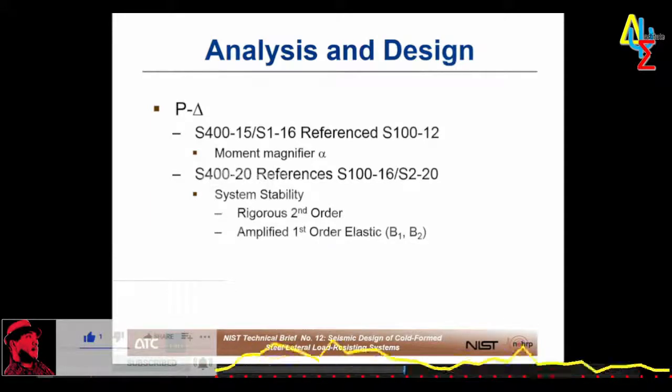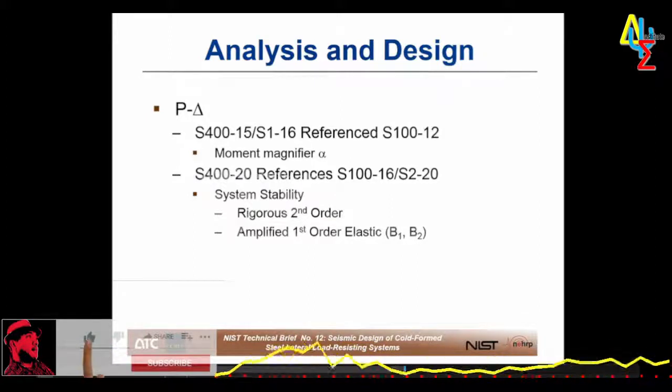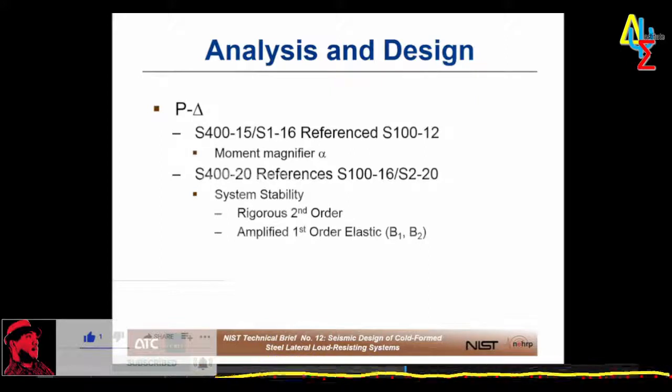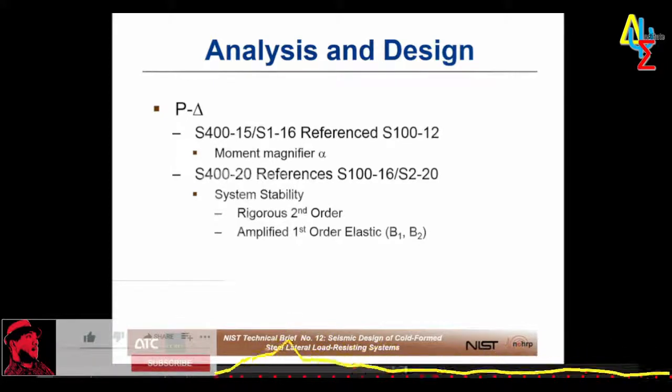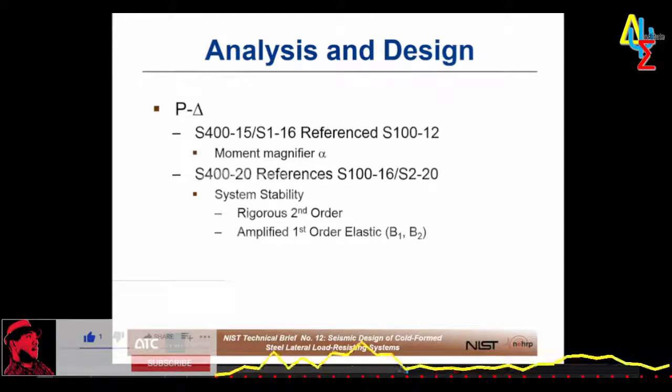So it's based on the deflections of the member itself. And then there's P-big-delta moments, which are based on lateral translation of the structure due to, in our case, seismic forces. So the B1, B2 analysis can be particularly interesting in our situation for single-sided strap-braced walls, where the strap tension generates strong axis moments. So it creates that bending that would require B1 amplification.